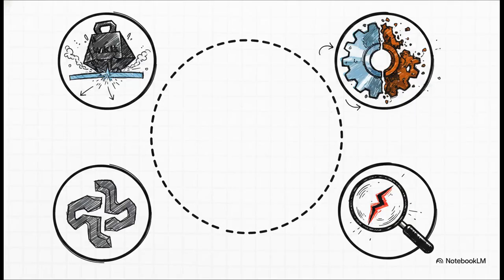So, what exact number do you actually choose for your factor of safety? Are we talking a factor of 2, a factor of 5? Look, it's definitely not a guess. The designer has to evaluate several key variables here. You have to consider the reliability of your material's properties, like will they degrade over time? You have to consider the reliability of the applied load. Could someone potentially overload the machine?